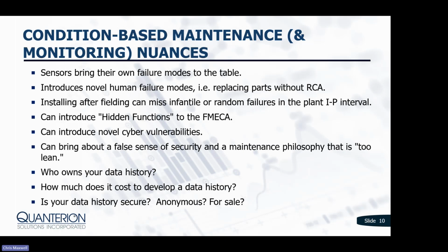You may be monitoring some refractory process or some high temperature rotating machinery. Your sensors might not be immune to those environments that you're using them in, right? Your process or your machinery may be perfectly happy with 200 or 400 degrees Celsius. The electronic sensor that you're putting in there may not really like that, or the insulation on the wires may not like that. Or there may be copious amounts of electromagnetic interference being generated within your plant that your sensors, if they're wireless, need to be immune to.